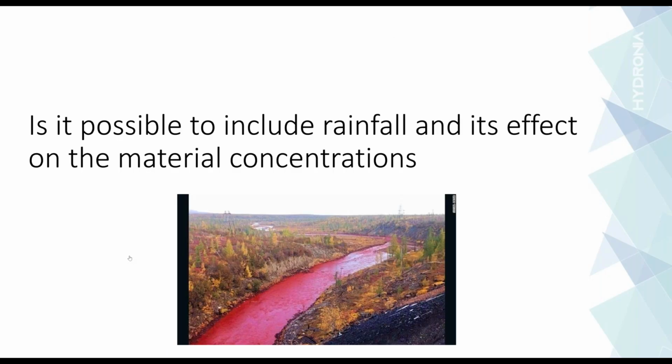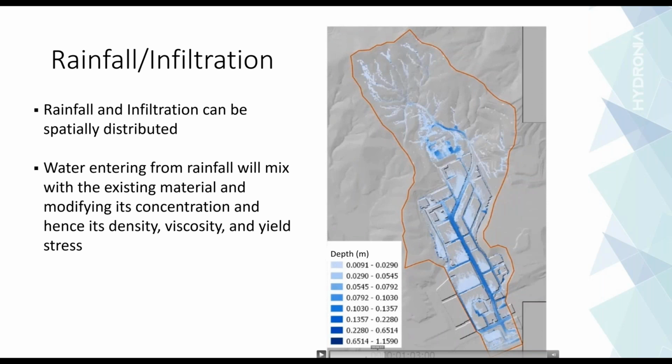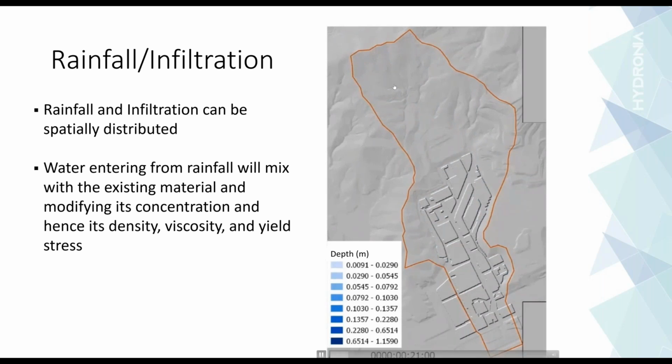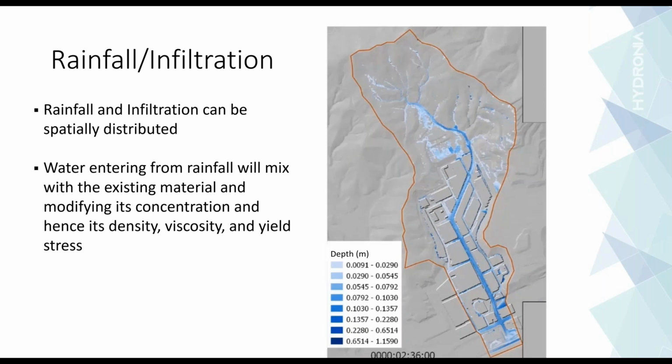So if you have a rainfall event, then eventually, let's say you are applying a rainfall to this area, and at some point the rainfall volume enters one cell. Once the volume enters the cell, then the flow will occur. The runoff will depend on how the equations deal with that in a cell-to-cell basis.